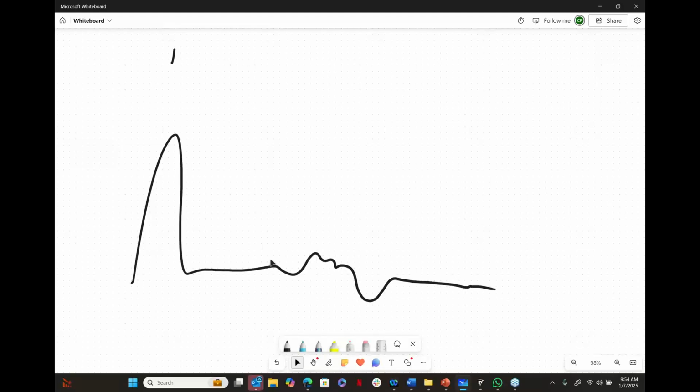I'm calling this reflection right here a double hump, okay? Different TDRs use a different software program where we connect the dots basically on the screen. So some TDRs draw their waveforms more sharp and have a point to it, and some are just a little more rounded. But regardless, all of your reflections do tend to rise and fall rather smoothly.